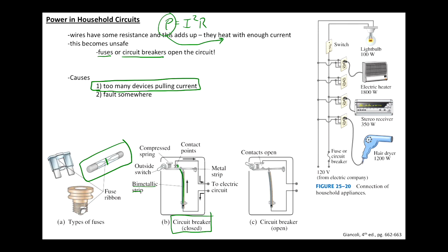Don't be like, I need to run all of this stuff. So this little device that keeps flipping, I noticed it had a number 40 on it. I was at Home Depot, and I saw similar-looking devices that say 60. 60 is greater than 40. Maybe it would allow me to do more. I will buy that one and put it in its place. And then you're like, everything is working wonderfully. I can do all that I want. Well, you can for a while, but all you've done is bypass whatever safety calculations were done, and now you've decided to go from a 40 amp maximum to a 60 amp maximum, 50% greater.